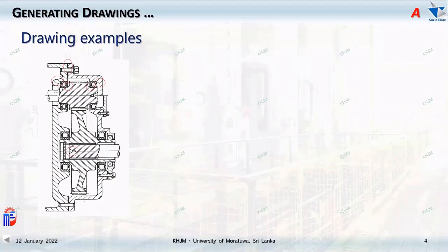So if there are allowances and you keep it floating, letting it be decided by whoever assembles the thing, that's not going to work. The design should simply be insert. If it doesn't fit, you go in the other direction. But if everything goes in and everything looks the same, then you're confused. You might assemble in the wrong sequence or the wrong way.